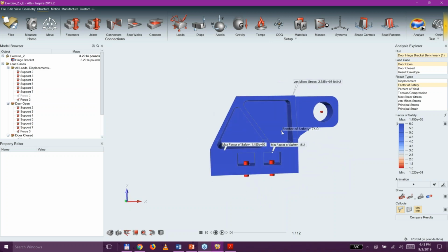And this is kind of the standard way of doing light weighting. You put a pocket in here. You do an analysis where there's no stress, you shave it off. Poke a hole through it. That's worked okay for years. But now it's time to kind of step up our game and take advantage of what we call simulation-driven design, which is using a simulation tool to actually help us design our part.